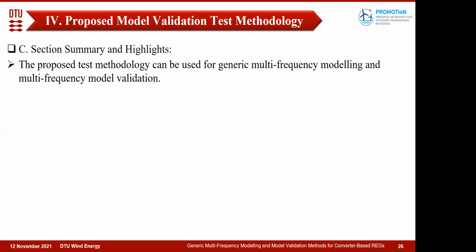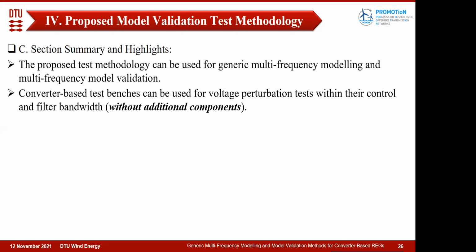So the summary and highlights: the proposed methodology can be used for generic modeling, and we can also use it for model validation, even of analytical models. Also, converter-based test benches can be used for voltage perturbation tests within the control and filter bandwidth.